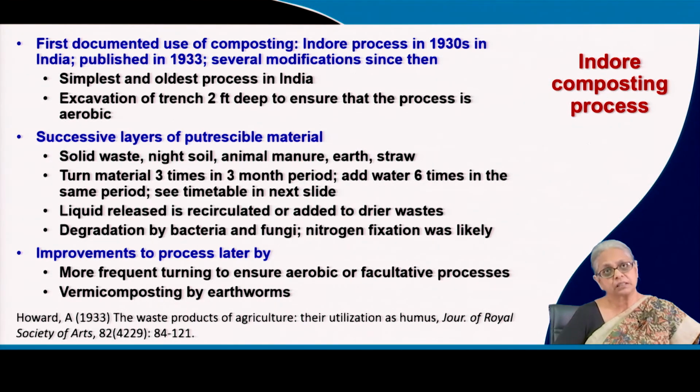So it's the simplest and oldest process in India. All it requires is that you dig a large trench up to 2 feet deep. You don't want to go more than 2 feet deep, because it's only up to 2 feet that the process is somewhat aerobic. Beyond that, it becomes anaerobic.